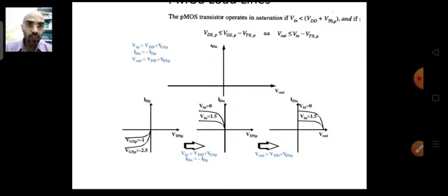So for Vin equal to 0, considering that IDN is equal to minus of IDP, previously I had plotted minus of IDP. Now you can plot it in the positive direction, as IDN on the positive side. Whatever characteristics you got for VGSP equal to minus 2.5, the same characteristics you can show for Vin equal to 0.